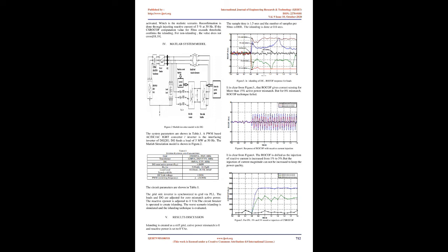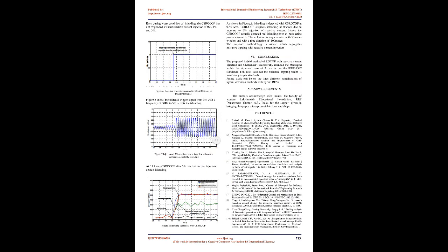3 Hybrid islanding detection method. The RCOF detection of islanding cannot work for active power mismatches between 0 to 15%. The frequency variation is not enough for RCOF to detect islanding condition at PCC in this condition. This is a passive detection method of islanding detection 12,13.